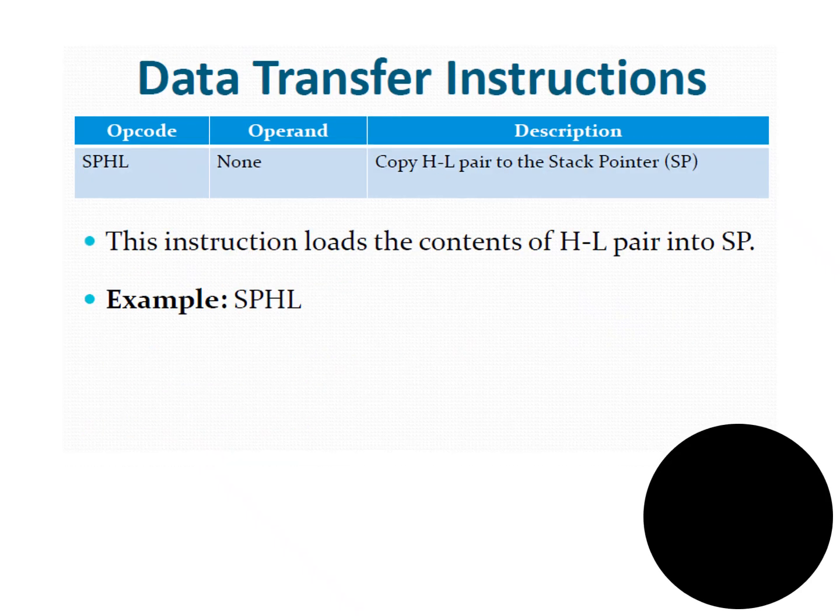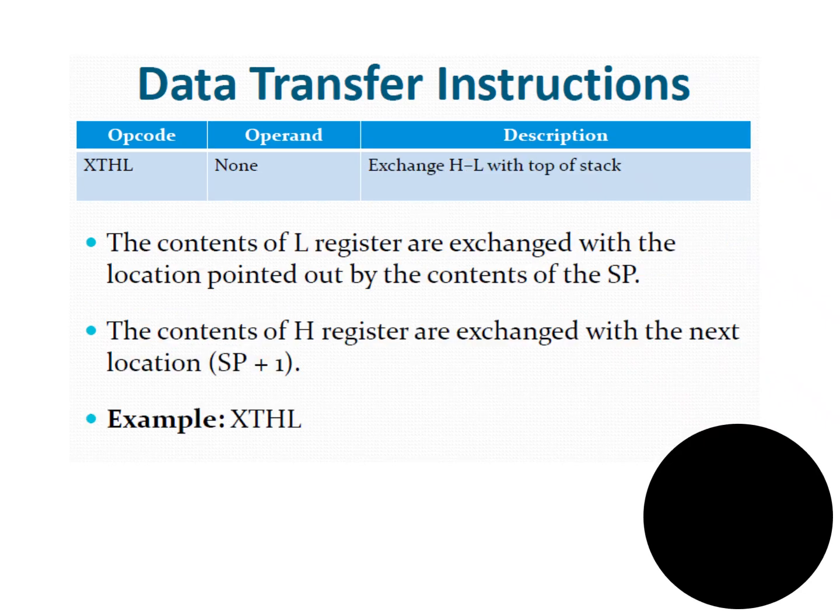Next, SPHL. This instruction loads the content of the HL pair into the stack pointer. Whatever content we have in the HL will be copied into the stack pointer. And next, XTHL, which will only exchange the HL register pair with the top of the stack. So that is what XTHL is.